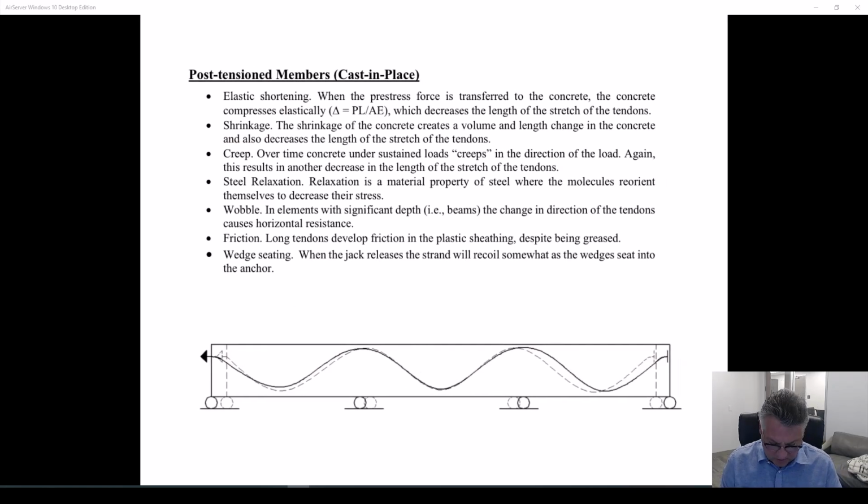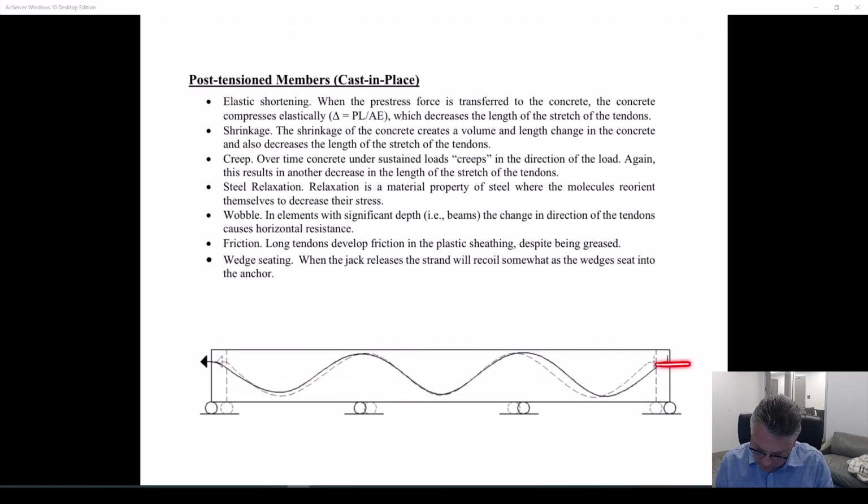After we have stressed, we're in such compression on the concrete that the shrinkage is actually causing more volume change. Instead of cracking and having a lot of that shrinkage change in length happening in little tiny pieces that all add up to maybe a half inch or 3/4 inch, the shrinkage portion in pre-stress concrete is all happening at the ends.